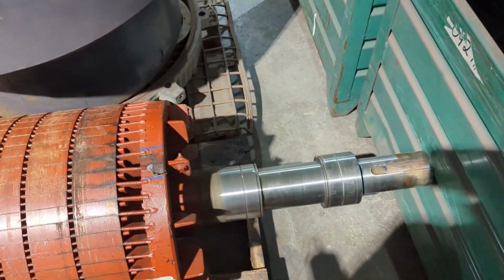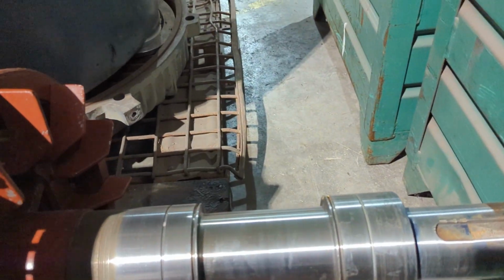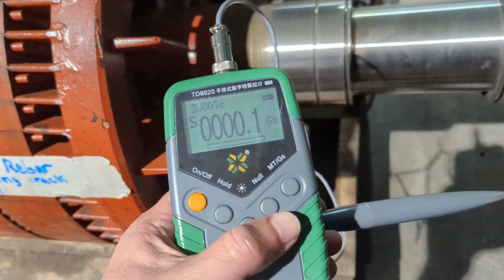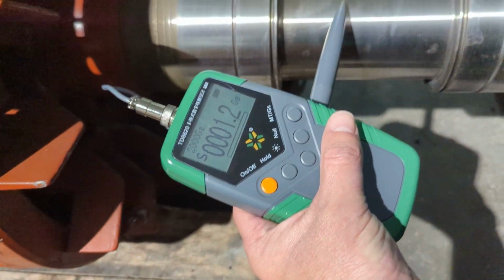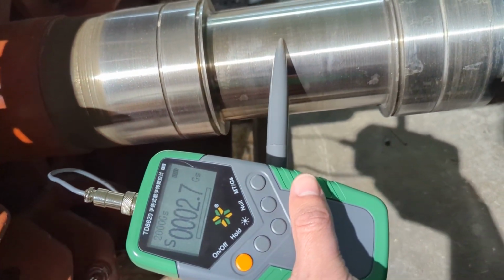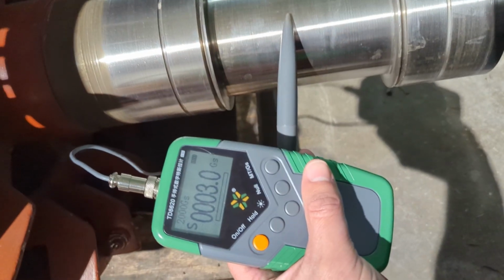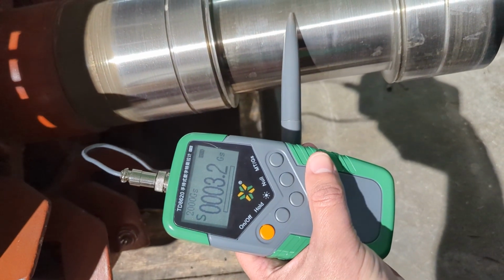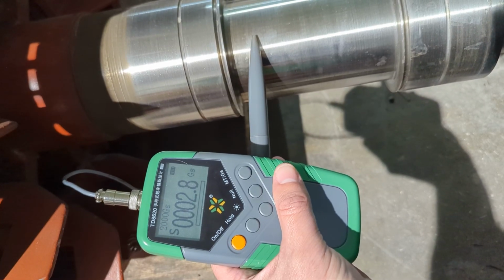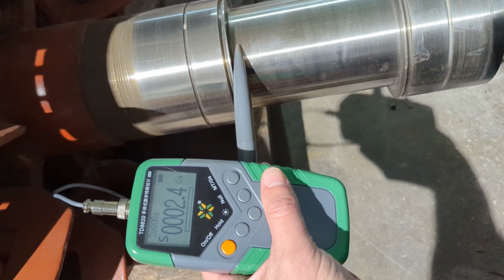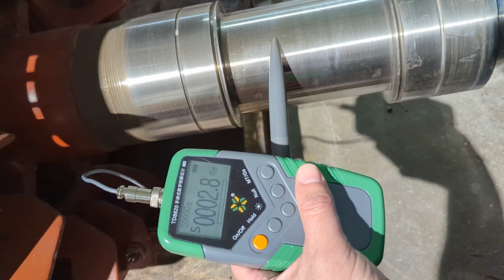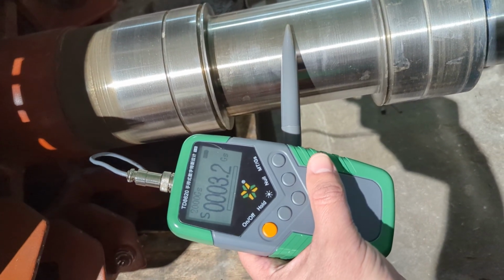Okay, so now on my rotor, this is the drive end. I've got my instrument and I want to take the measurement, make sure it's on 0, and then remember, because it's a radial probe, I want to go perpendicular to my measurement. Oh, and look at that, that is more than 2 Gauss. I can move it around slowly and see it will take some time to settle, and you'll see over the length of the shaft it does change. That's quite normal.